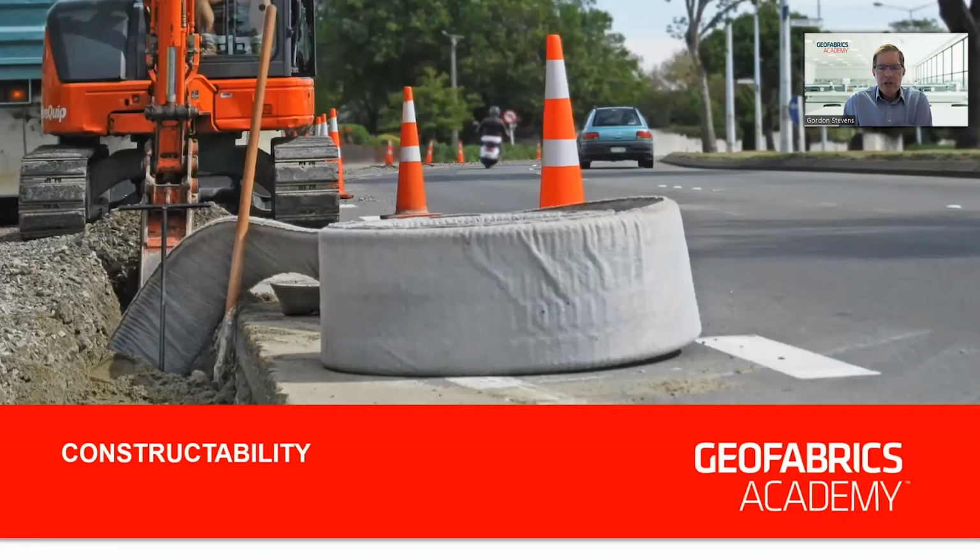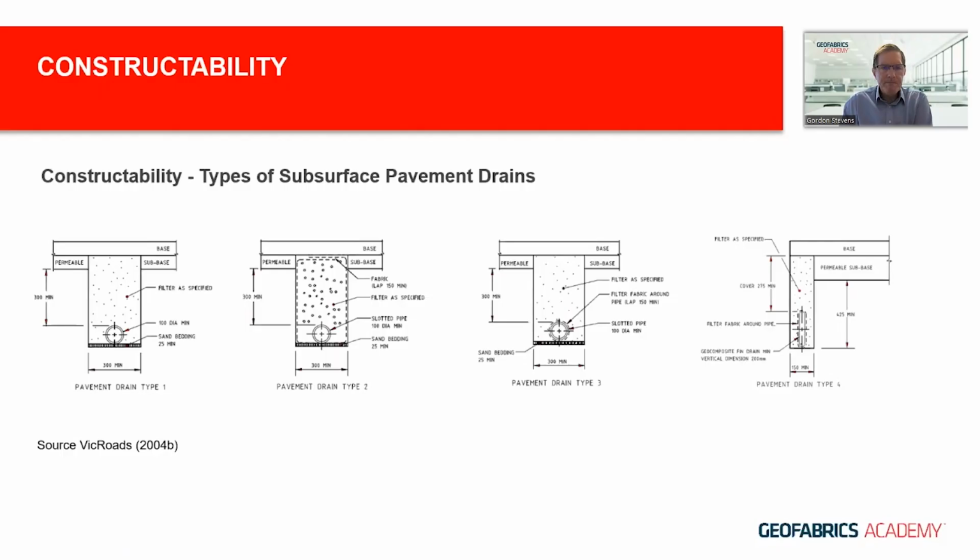So moving on to constructability. Within the guidelines, they show a number of different types of pavement drains. So we've got type 1 over here, where you're looking at a granular filter, so a single stage system with a round pipe as your collector. Pavement 2 is a geotextile wrap drain, so that would be a 2-stage filter system.